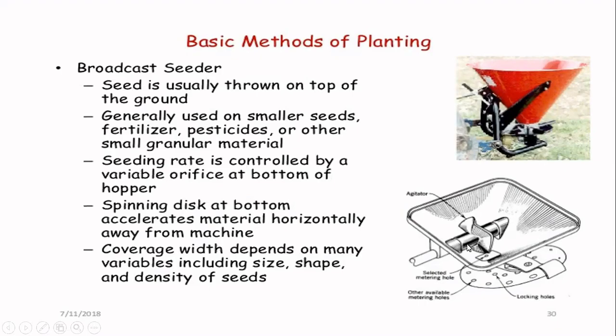So it is not a seed metering device. You see, it is called an agitator. Agitator means you put seed, and the seed will never move because it has 2 kilograms of seed. It will act and move in a uniform manner. So the wheel is rotating. When rotating, the seed will automatically fall down. Very slowly it rotates, so seed will automatically fall down to the seed metering device.